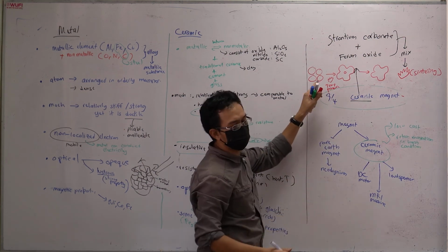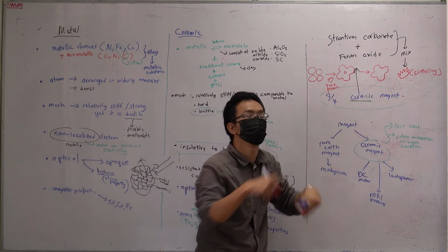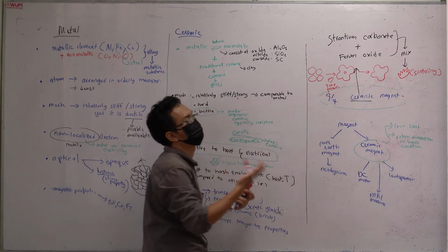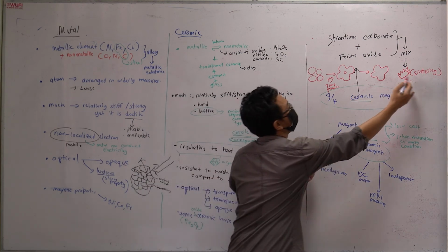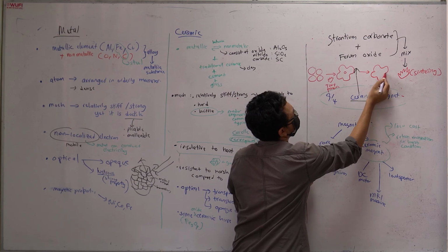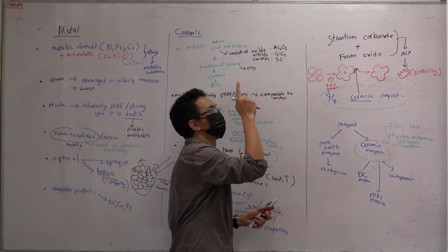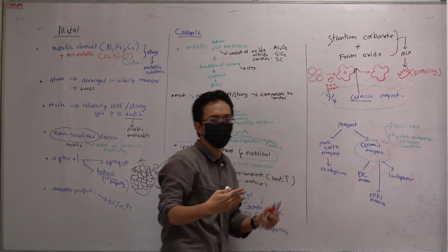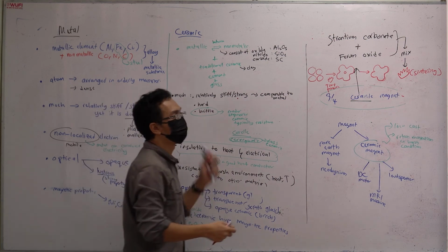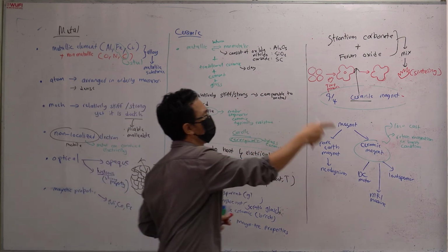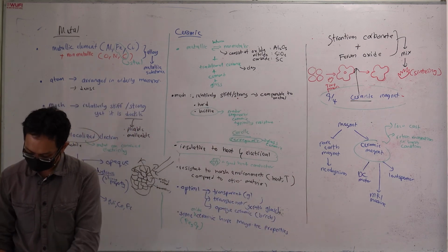The temperature they use is not enough to melt the powder. That's why it doesn't melt, it doesn't flow. It's enough to sinter. This is what we call sintering. You don't melt, you just fuse. So you can still see the retained shape. It's not melted, because you cannot put the temperature to the point that the thing melts, it's difficult. So that's sintering, and then you get the ceramic magnet. That's basically the ceramic magnet.